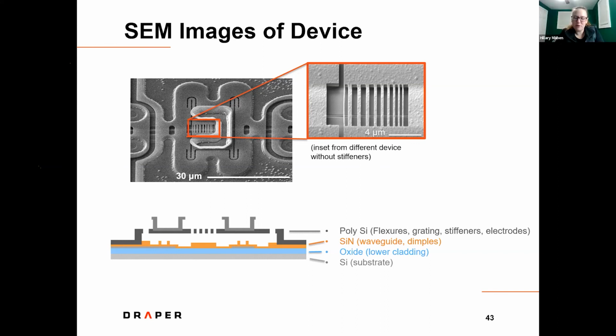Okay, and Frank was asking how large an angle can be scanned with the Draper MEMS-based array? One of the nice things about this I didn't get into is it is dependent on the lens. You can put any lens you want in front of this chip and you can get any angle that your lens can deliver. So unlike an optical phased array or a lot of techniques, right? It's just like a camera. I can put a wide angle lens in front of it, or I can put a telephoto lens.